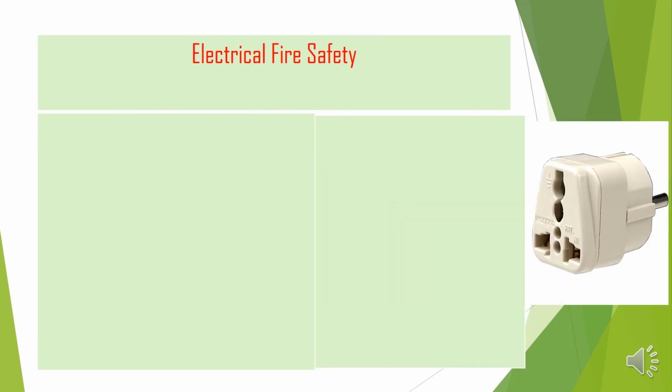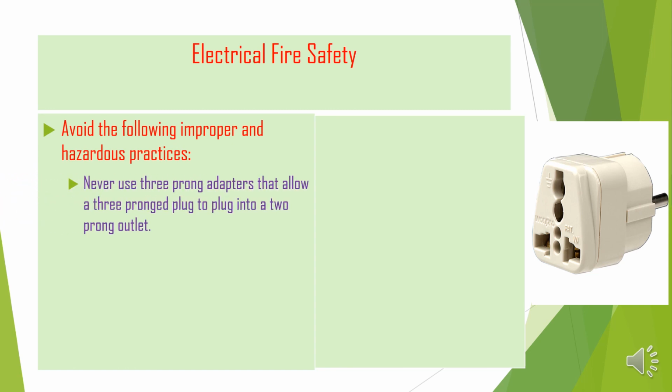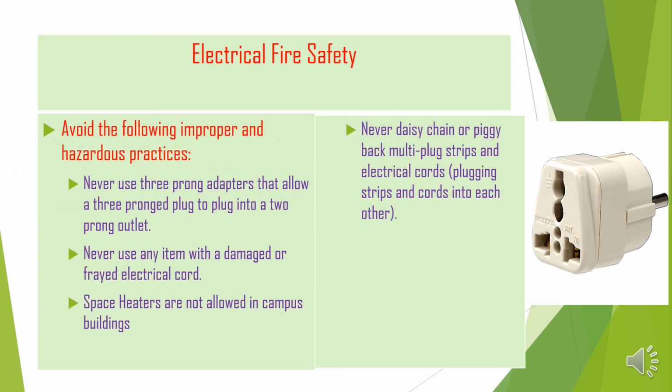This is what we are talking about. Never use three-prong adapters that allow a three-pronged plug to plug into a two-prong outlet. This is one three-prong adapter. Don't use it. You have to put the three prongs inside the wall itself. Don't use this one because it's a very important source of fires.